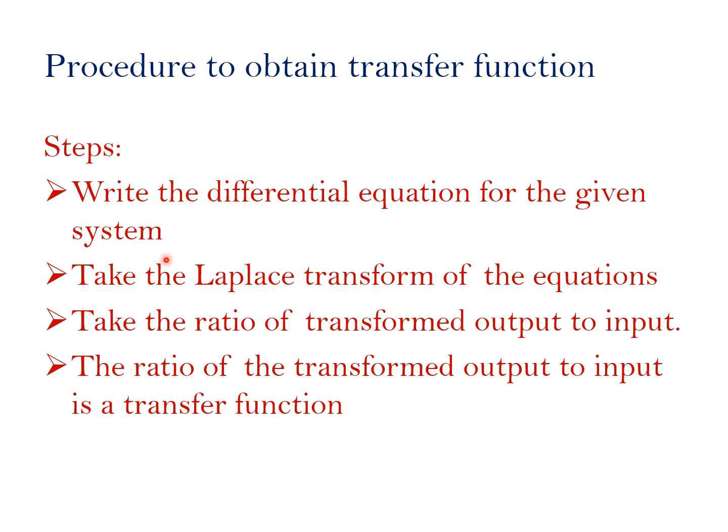that is very must. Next, step number 2, take the Laplace transformation of the equation. Then step number 3, take the ratio of transformed output to input. The ratio of transformed output to input is the transfer function. So these are the steps needed to find out the transfer function.